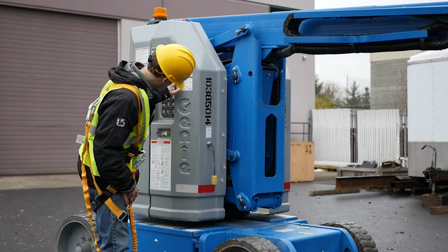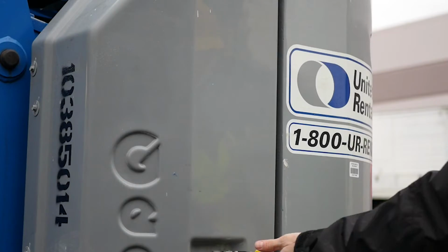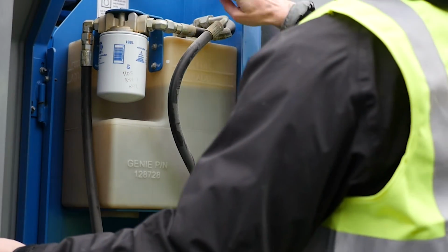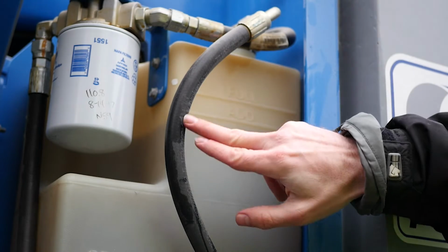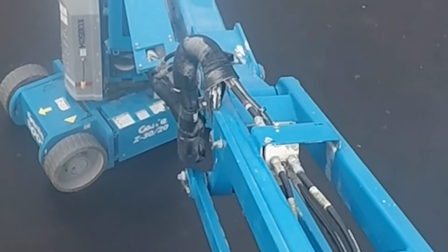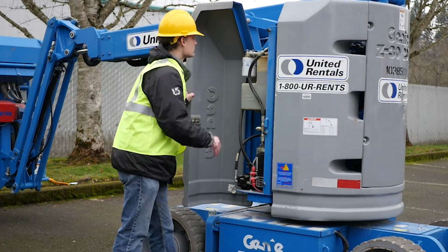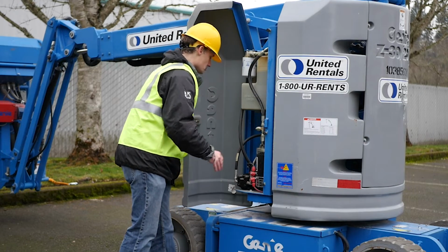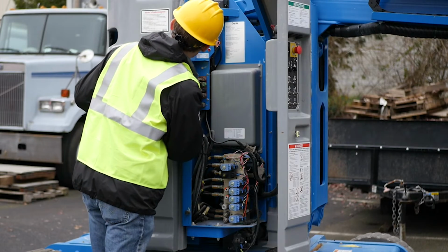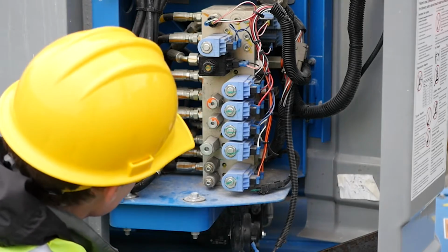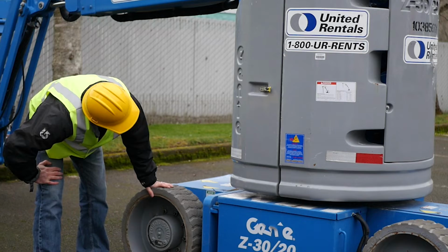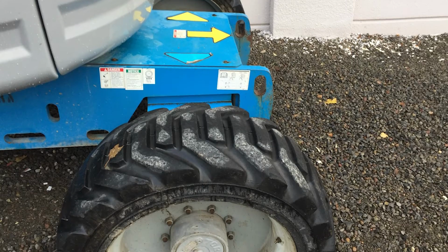Check for validation that the vehicle annual inspection is current. Check hydraulic and pneumatic systems for observable deterioration and excessive leakage. Check the fluid systems levels. Pneumatic and hydraulic control systems operate under pressure. Leaks in these systems can cause injury to employees, expose them to hazardous chemicals, and create a slippery and unsafe work area. Check the electrical systems for damage, signs of excessive deterioration, dirt, and moisture accumulation. Check the tires for proper inflation, if required. Inspect the wheels and wheel fasteners.